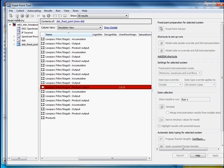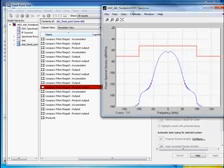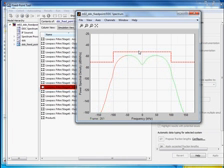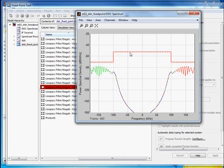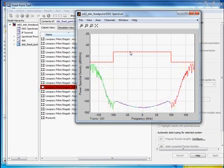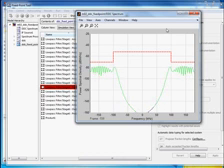So what we'll do here is we'll still keep logging data, but we'll override the fixed point settings we put into the model and put in doubles. So we'll go ahead and do that. And now we will rerun the simulation. So now we should get good agreement because we've gotten rid of the fixed point settings. We're getting good agreement between the two models. And let's accumulate data to get a better fix on the necessary dynamic range.